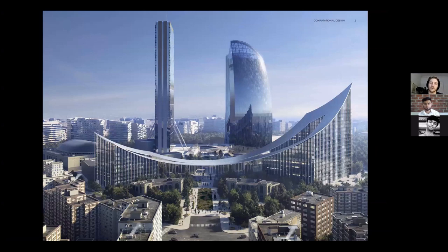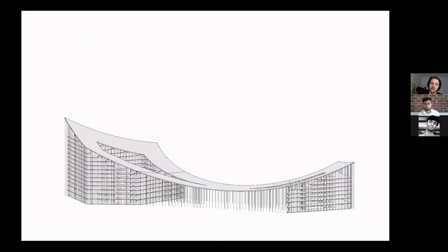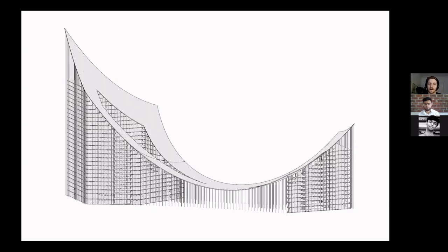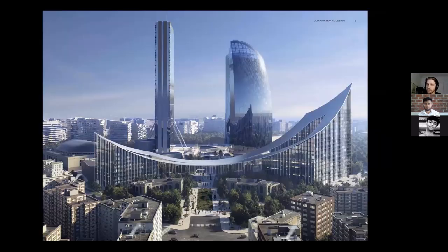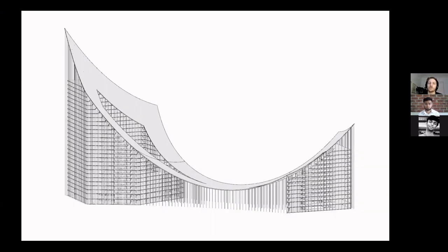And what we did with these was that we then made links to our BIM software, in this case, Revit. So whenever the architects were ready to say, okay, now we lock the geometry, this is what we're going with, we could click, and we had generated the entire geometry in Revit. We had it in our structural analysis software. So basically, we did a lot of footwork, you could say, to build this parametric model. But in the end, we could check hundreds of variations, and we could just say, let's go, when the architects gave the final go.